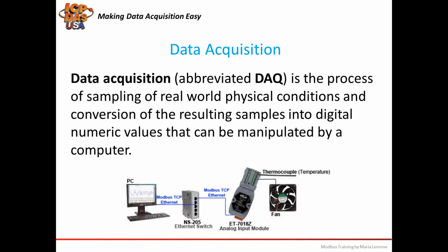Modbus RTU and Modbus TCP are protocols or languages that devices can communicate over. RS-485 or Ethernet refers to cabling that protocols can communicate over. Sensors are attached to data acquisition equipment, which can provide information that a computer or controller can use.